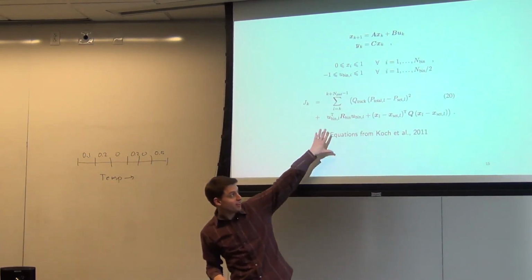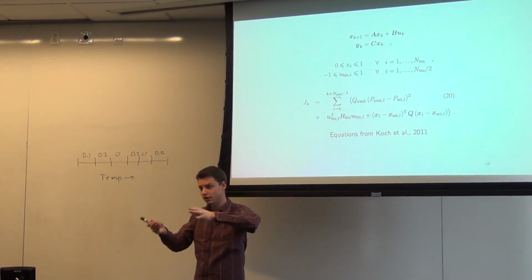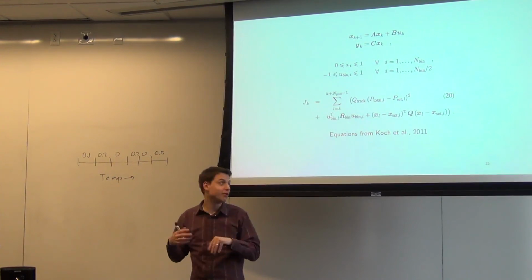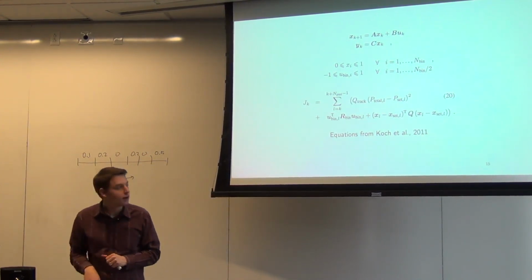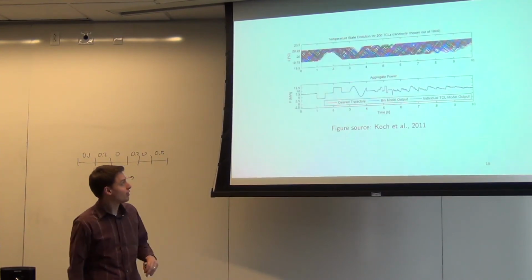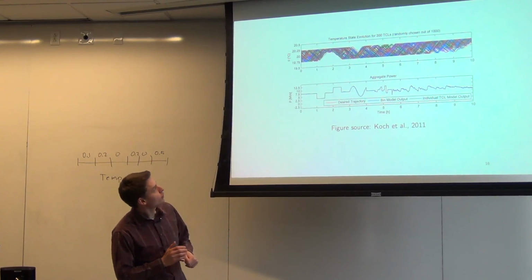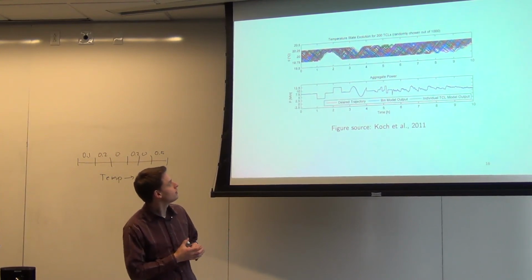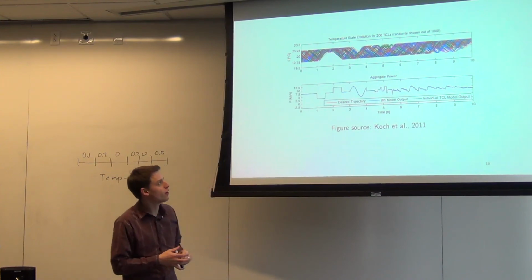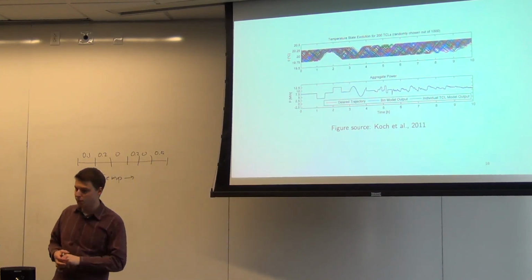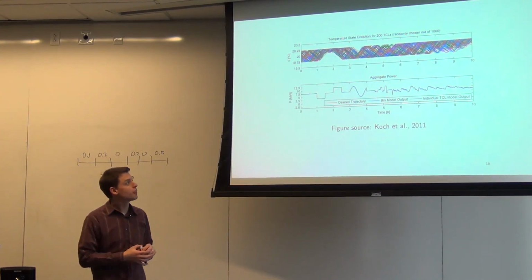So this control objective is exactly model predictive control, and it's applied to this dynamical system of air conditioners or refrigerators communicating to figure out what to do. And it works really well. What they're able to do is, using, I think, 1,000 different air conditioners, or TCLs, which stands for thermostatically controlled loads. That can be refrigerators or electric heaters or air conditioners.